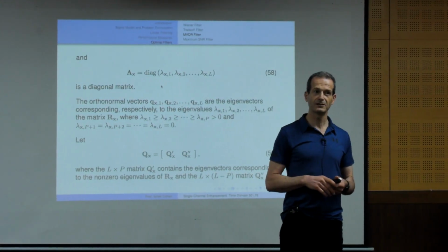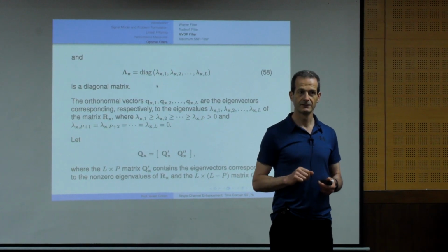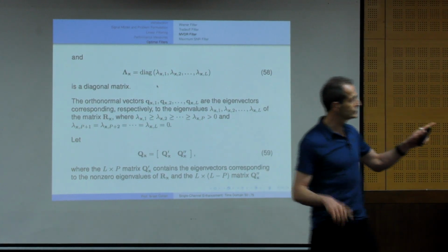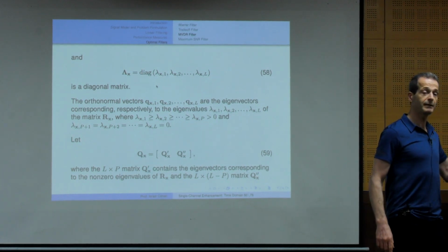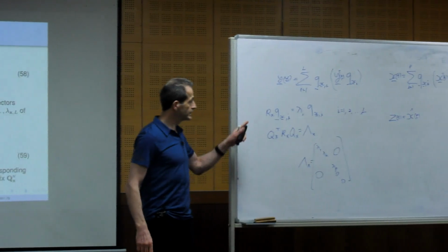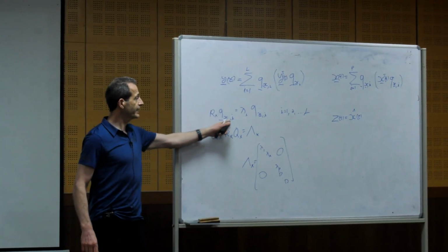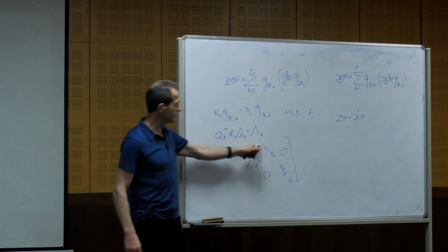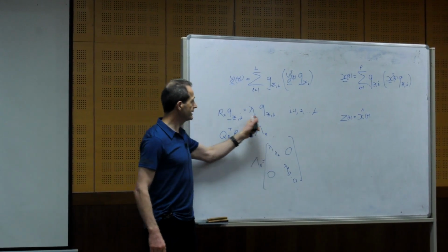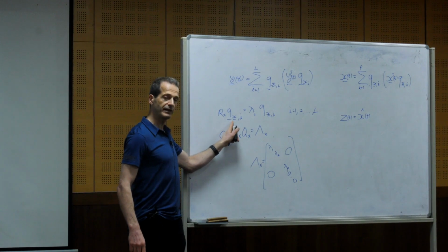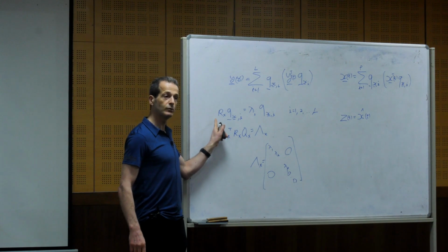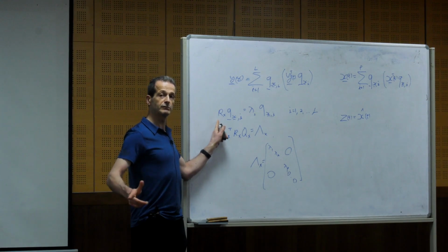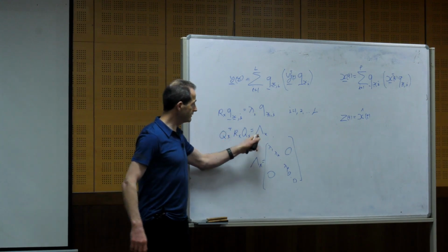Okay? So if we think about it, I didn't say that we need to implement MVDR in the Fourier transform. So maybe it contains all frequencies. But maybe the eigenvectors, the first eigenvectors, so if I find the eigenvectors and eigenvalues, I see that the rank of Rx is P, which is lower than L, even though it contains all the frequencies.